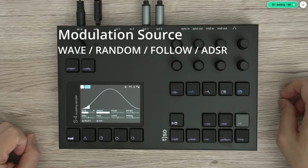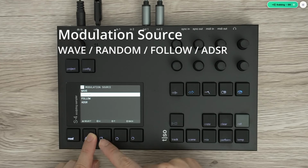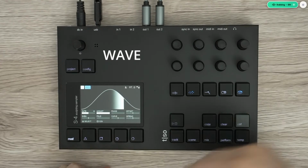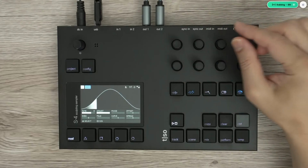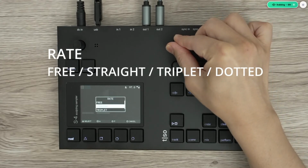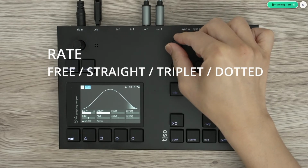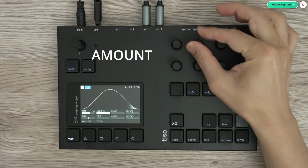There are 4 modulation sources: wave, random, follow, and ADSR. To switch the wave source, tap the modulation button briefly, then select with the select button. Wave allows advanced and complex modulation like LFO and loop envelope. Rate controls the cycle. Select free, straight, triplet, or dot by pressing and turning the knob. Amount adjusts depth, and phase adjusts the phase of the modulation.